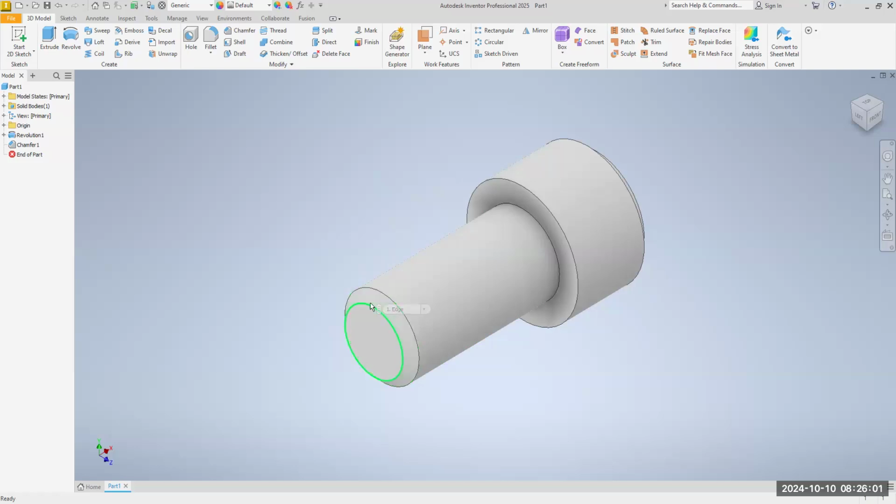We have a chamfer here so that it can center into the hole. In other words, it's going to screw into a hole that's threaded or a nut, and that chamfer helps to center the screw. So it makes it easier to screw into a nut or a threaded hole. One more time.